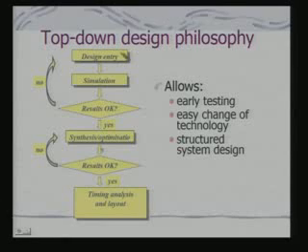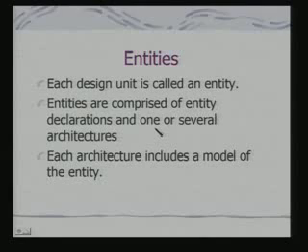So, the design philosophy is you have a design entry, simulate, if it is okay, else modify, then you synthesize and optimize, again do the simulation, fine, and then do timing analysis and layout for coming to the final form. Okay. So, early testing, easy change of technology and structured system design. So, what you see is that before even coming to the device level, which is the layout, we can do a simulation and testing of the system to know its correctness.